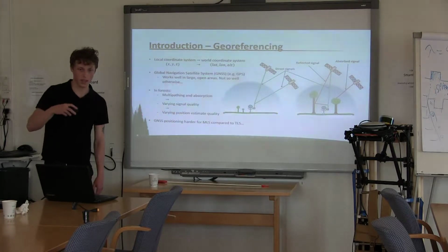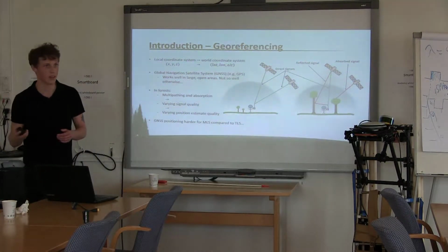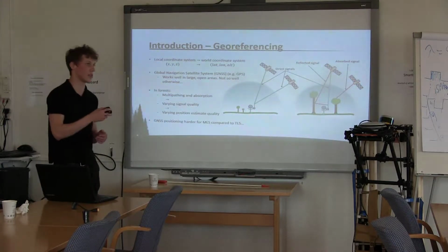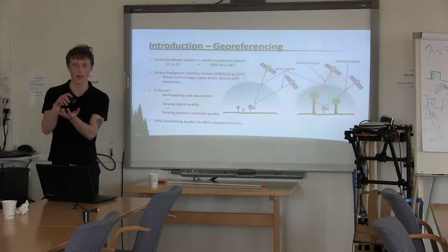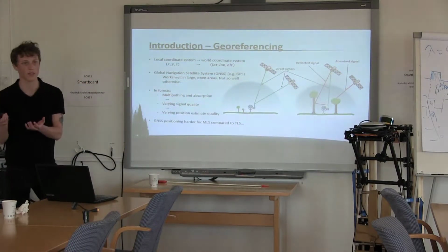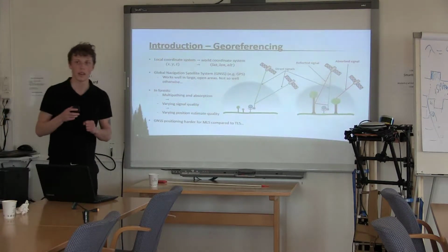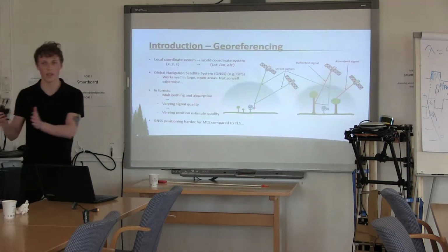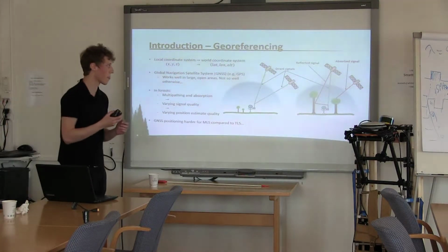But in these cases, you usually want to do something called georeferencing, and by that I mean that you want to put your model, your point cloud, in a world coordinate system, like latitude, longitude, and altitude. You don't want it in local coordinates. So you want to know where you took your point cloud data.